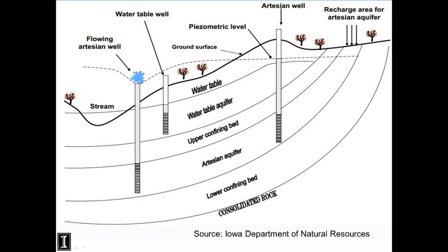When you put a well in this deep aquifer, like here's the screen for this, the way they've drawn this, it forces water to come up to this potentiometric surface level. It's the pressure caused by the recharge area over here on the system. And if your well's low enough, it'll start flowing. There are many areas in the country where there are flowing wells. I know there are areas where the water level is close to the surface naturally, but maybe not flowing. A large recharge event, like a flooding event in one part of this area, might cause a well to flow for a week or so.